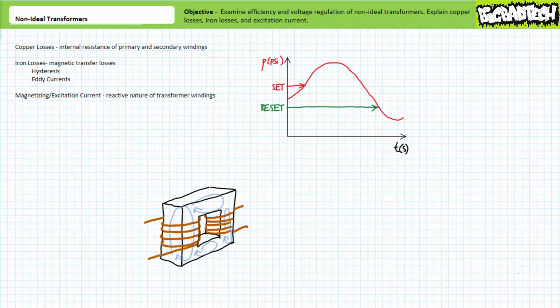Indeed there would. These inadvertently induced currents are known as eddy currents, and like the boils of a turbulently moving liquid, don't really go anywhere, but rather churn about and make it generally harder for the system to operate smoothly. These eddy currents inside the resistive core also result in power losses in the form of heat.